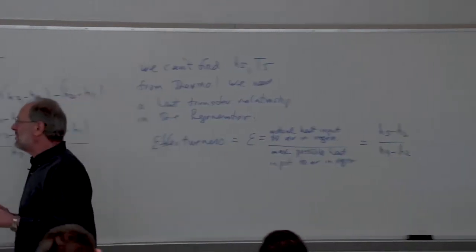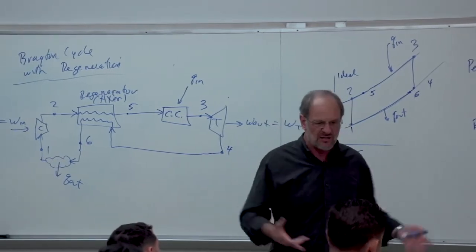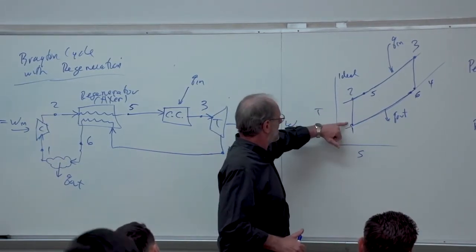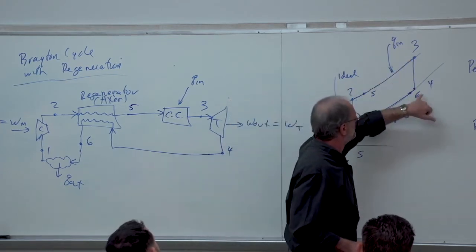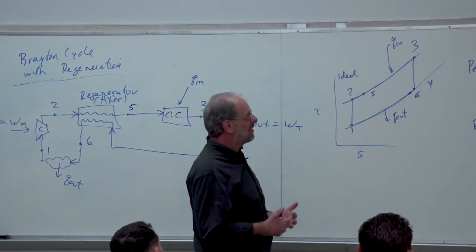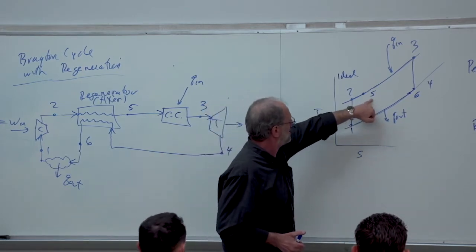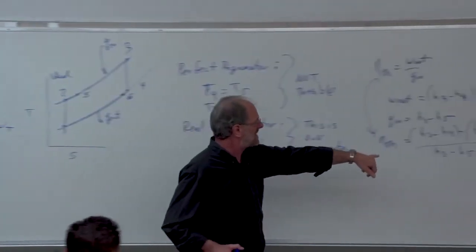We're going to go through our Brayton cycle in exactly the same way that we've already talked about. Whether it's ideal or non-ideal doesn't even matter. We're still going to go through a compression from 1 to 2, perhaps 2s and 2a. We're going to go through expansion from 3 to 4, again, perhaps 4s and 4a. But ultimately, we're going to need to find the enthalpy at point 5, right? Without the enthalpy at 5, we can't find the thermodynamic efficiency.